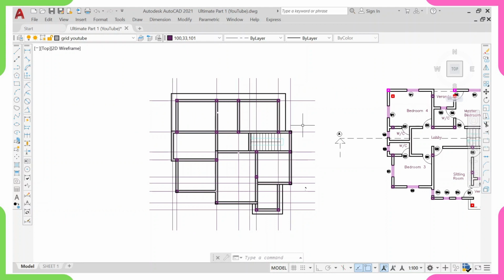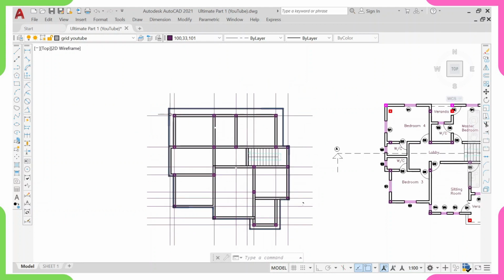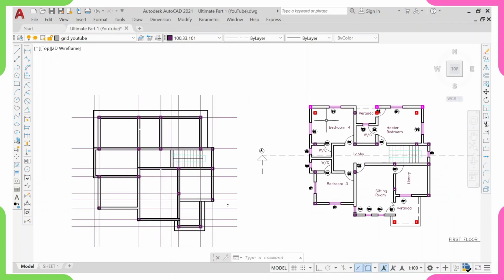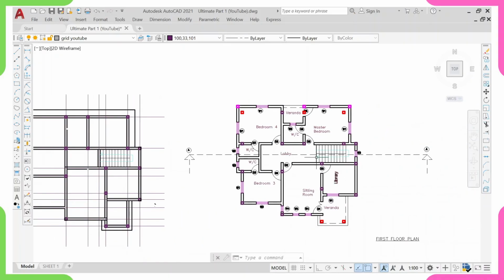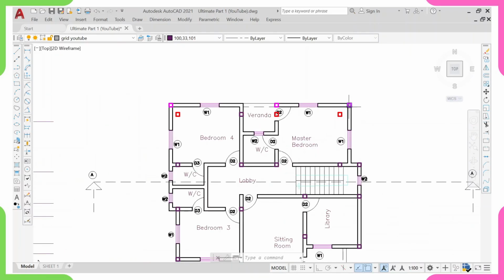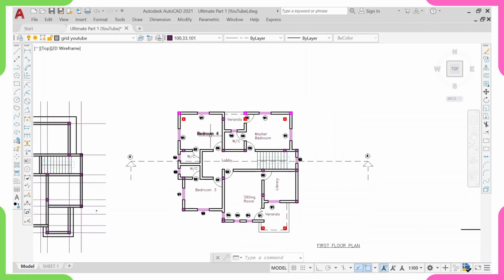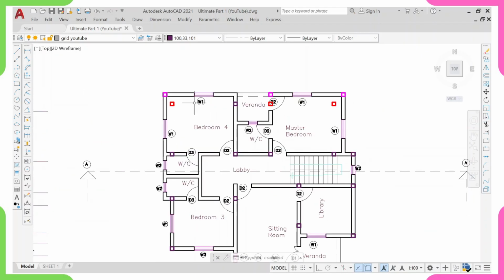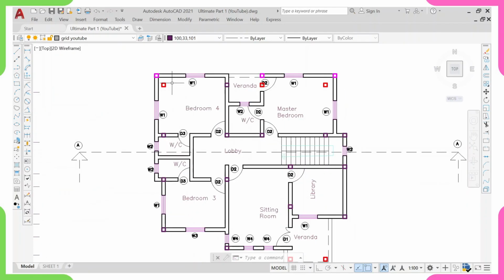And in that previous video, I shared the governing principles relating to column placement, beam, and also paneling. We found that this column, this column, this column, and this column will terminate at the ground floor. They will not continue at first floor, which are these columns on red color. Then we now introduce a new column, which are these ones on magenta, and these are called floating columns. Reason is because they did not start from the foundation level, they started at the second floor. So any column that doesn't start from the foundation level is called a floating column.